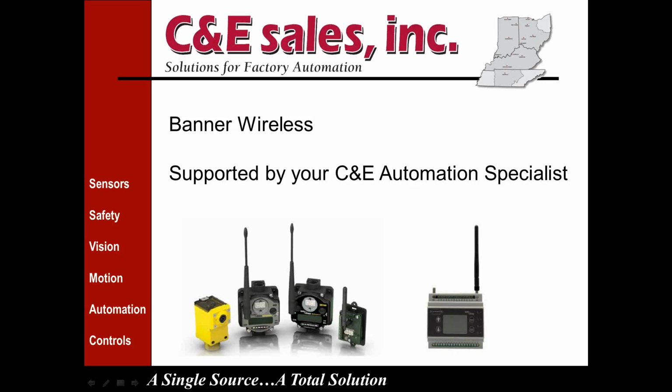No trees, no obstructions. Typically in a manufacturing facility, where you've got these radios maybe in a panel or mounted on a column or in a wall, a few hundred feet commonly. But that's why it's really important to do the site survey to understand the signal strength you're receiving, based on obstructions that you really can't account for. Absolutely. And C&E has hardware, so if you have an application in mind, we can bring hardware out and do some site surveying. We've got 7 automation specialists scattered throughout the C&E territory. All of us have Banner wireless equipment and can easily come out and do the site survey for you to help you understand the true signal strength. It's hard to account for all the different noises and walls in factories.